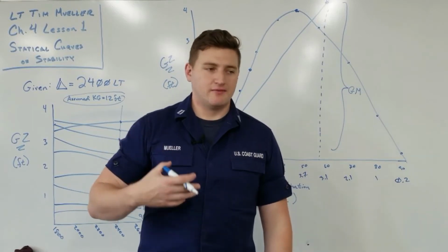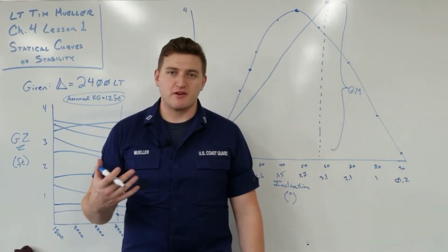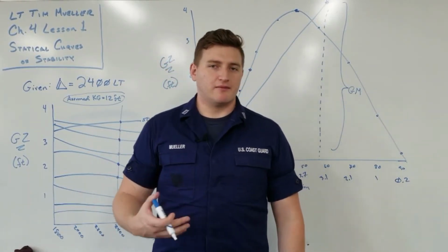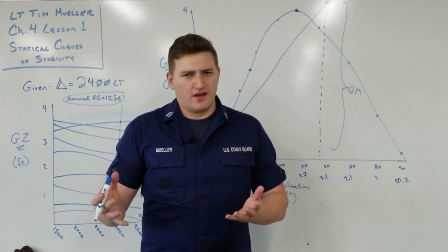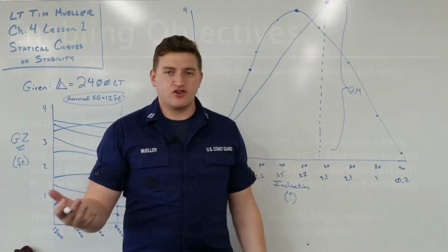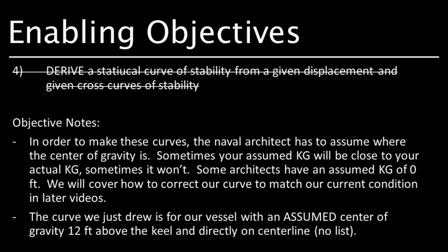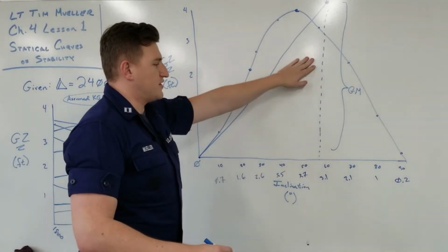Maybe you need, according to your DC book or your ship's manufacturer, to obtain a GM of 8, let's say, in order to have a stable base for your crane. There's a lot of information that you can get from these charts.